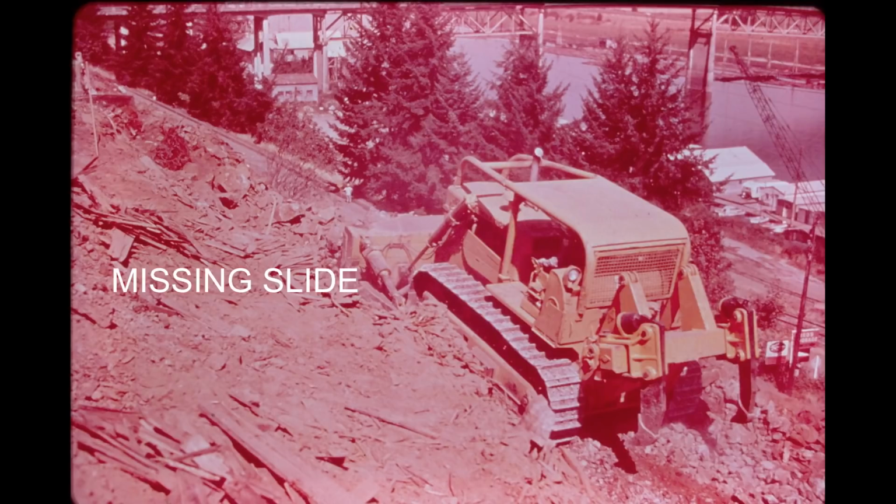International uses 4 basic types of sprockets. A 3-piece segmented sprocket is used on the TD25C. The segmented design allows sprocket removal without removing the track frame. If pinion shaft removal is required, the smallest of the 3 segments can be indexed with the pinion shaft cover. When the segment is removed, the shaft is easily accessible.